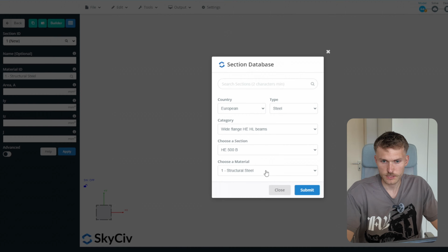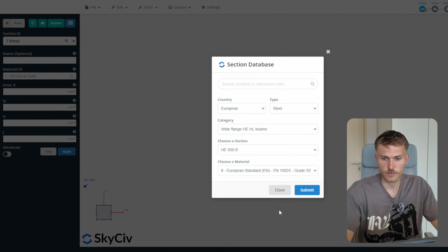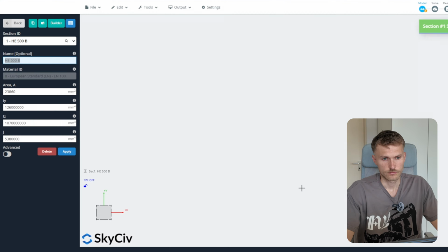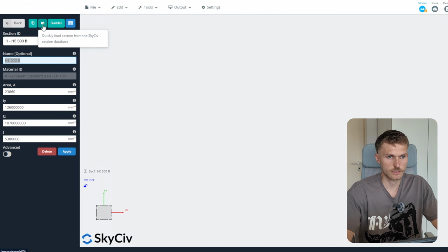Here. And then we select the material that we just created and click on Submit. Okay, great. Now let's do the same thing for our rafters and our wind braces.